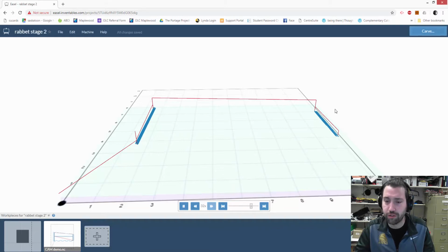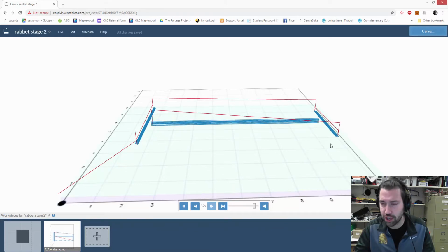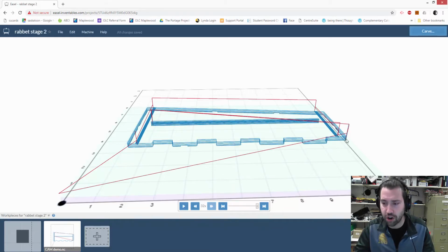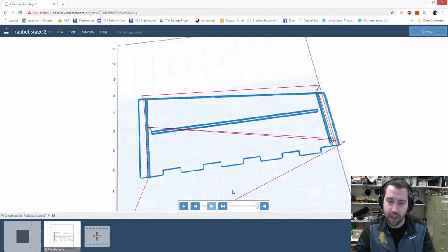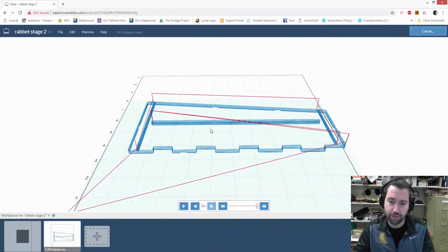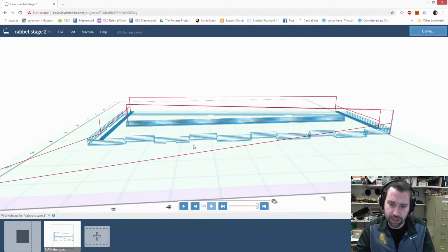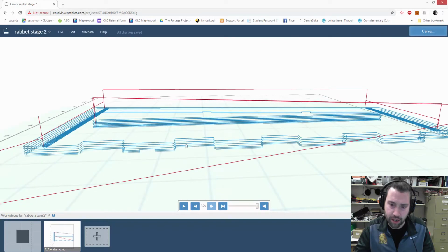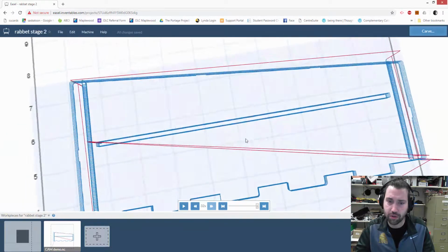and it doesn't really show us the full preview of where the stock is. It just shows kind of up to the end of where it's carving, which we can see is the 11-inch mark. There is really 1 more inch of stock on this side, and we've got maybe about another 1/2 inch of stock up on this side. And if we look at this in profile, we can see that there were a number of depths. It looks like 6 different depths on the way down, and we can see where the tab would be left in some of those different locations.